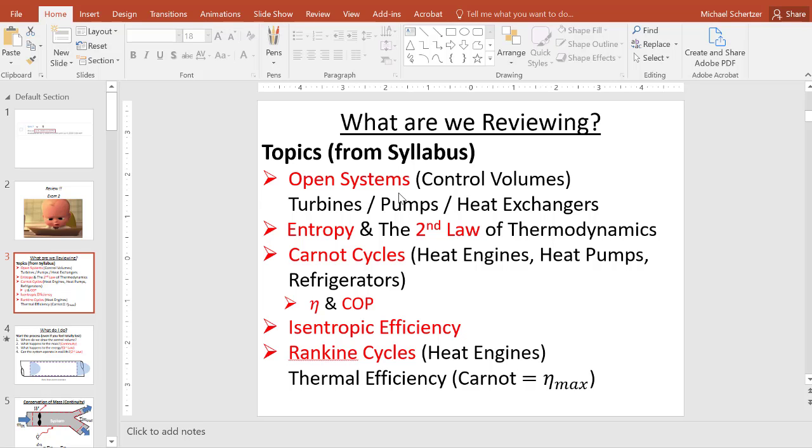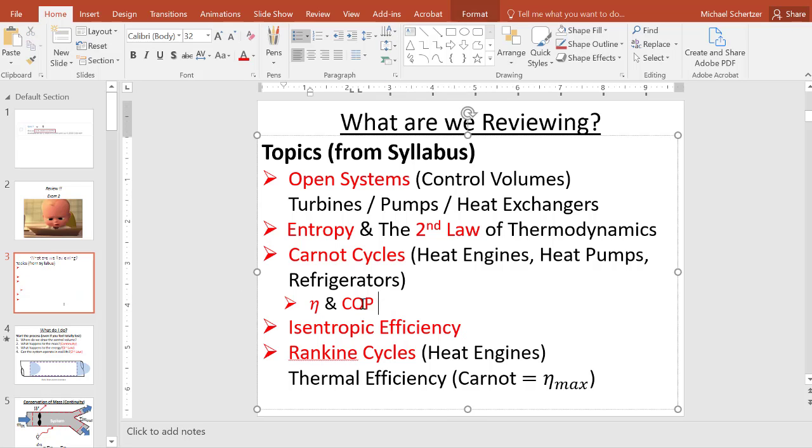So we defined what a heat engine is, what a refrigeration unit is. We talked about how to get the ideal version of performance out of particular processes, right? So that we have that sigma dot term, which goes to 0. We talked about Carnot efficiencies and Carnot coefficients of performance. We talked also about ideal turbines and pumps and how when we do a second law analysis of those components, if we make a series of assumptions, it turns out that there's no change in specific entropy across ideal turbines and pumps. So that's a way that we can fix a state coming out of an ideal pump.